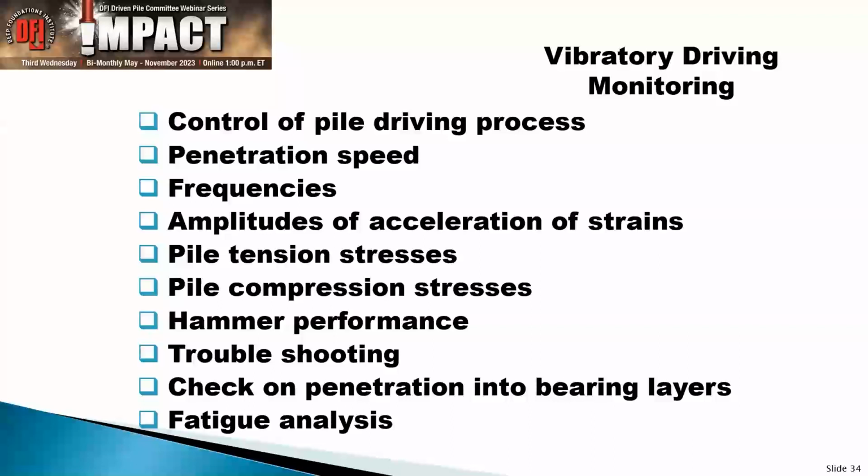Again, a misnomer. But especially when we are using vibratory driving, a lot of that has to do with offshore pile driving. And in the offshore world, steel fatigue within the steel piles is a very important issue. And what people are worried about is what I mentioned earlier about the fatigue in the soil.